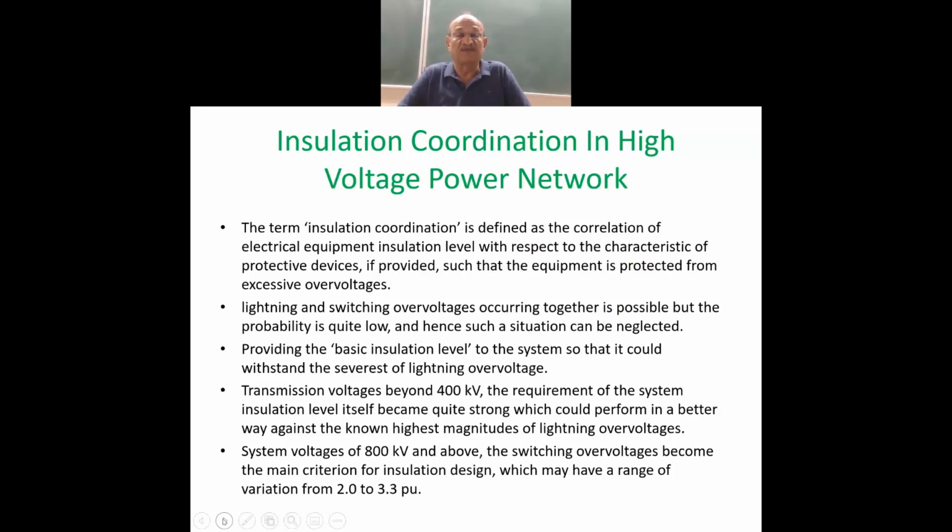So the power frequency voltage or current is not able to pass through, but the high frequency transient overvoltage in the form of a traveling wave would get grounded at these zinc oxide arresters. So this is a characteristic of zinc oxide arresters, or zinc oxide material.